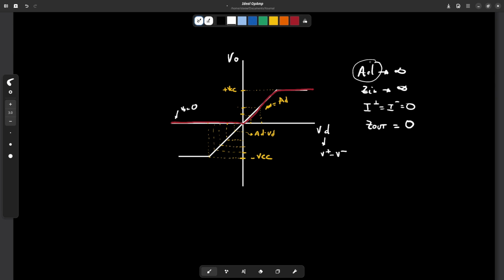Okay, so very high gain. It is not suitable to use as an amplifier. We usually use this type of amplifier in open loop for comparator purposes, okay? And if we want to use the operational amplifier as an amplifier, we should use negative feedback topologies like inverter, non-inverter, and so on, okay?